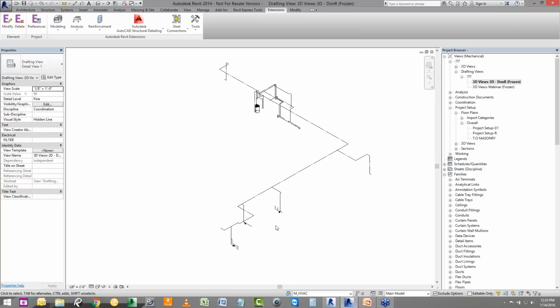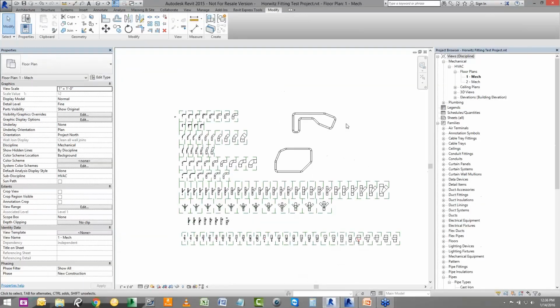So now that we've done taking a look at that, I'm going to go ahead and go into a different Revit project. And I'm going to show you guys an example of fittings and lookup tables and how a lot of that works. Here we are inside one of my test projects. Whenever I am creating fittings or modifying fittings, I like to establish a test project like this, and it usually is set up similar to something like this, where I have a test area to test the functionality.